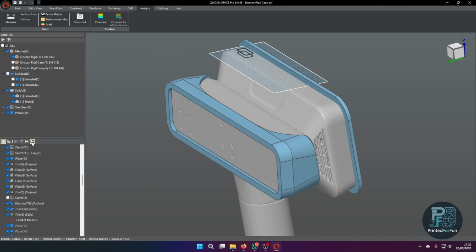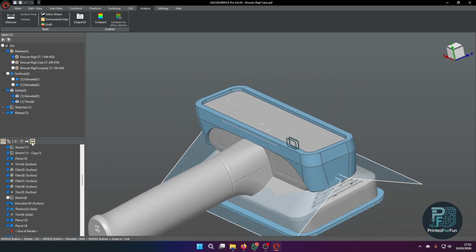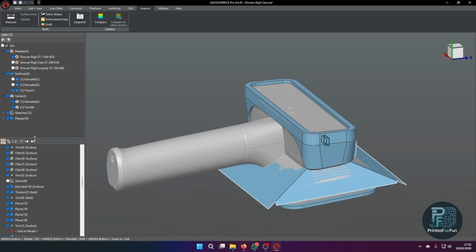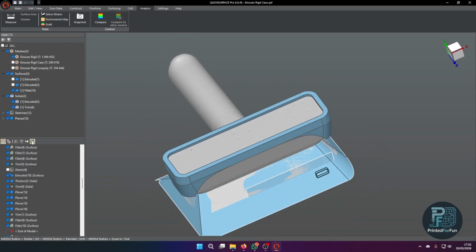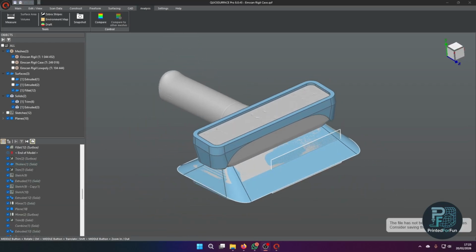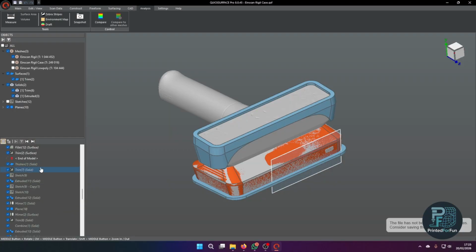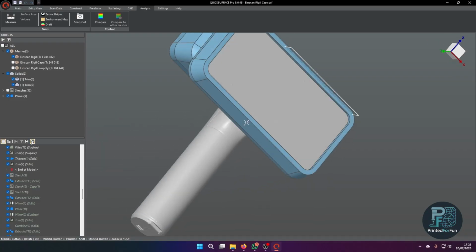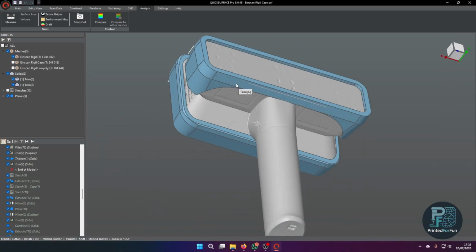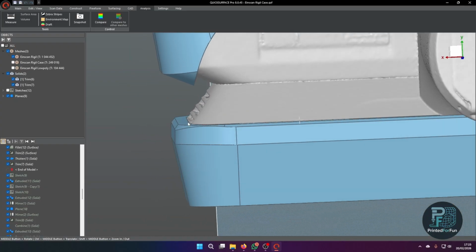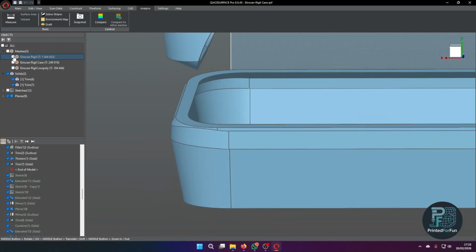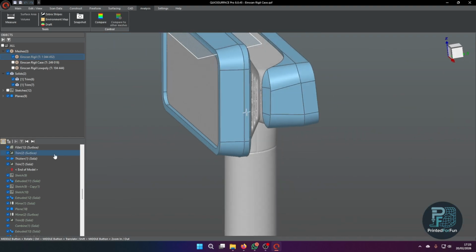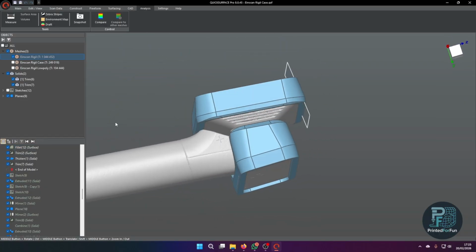Now, as this part is finished, I can go back to the top part where basically the whole approach will be the same. I can again trim my surfaces at the variable fillets and trim again all the surfaces to one cohering surface, thicken it and trim it to create the upper sleeve. As you can see here on the side, I created the sleeve so I have, of course, overlap, so it mechanically locks to the scanner, but it doesn't obstruct the venting fins or the vent grills.